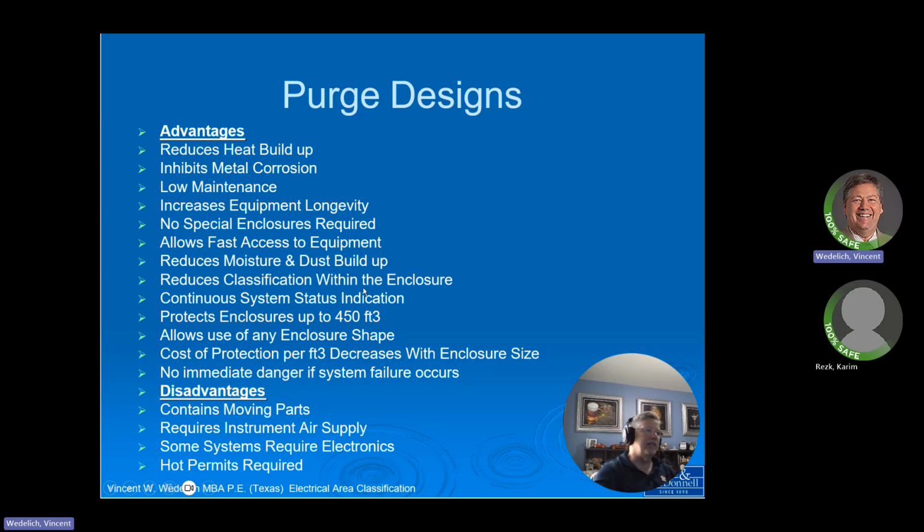Reduces classification within the enclosure. That's true. One division, one classification, not two, right? Except for an X purge reduces it all the way from a Div 1 all the way to general purpose, because it does that. It has no electricity. It has no power.